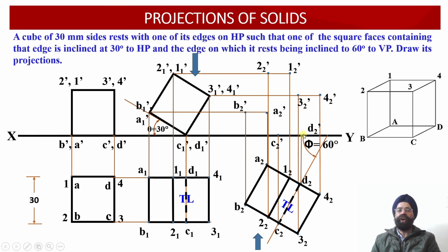But which of the edges will be drawn using object line? Which of these edges will be joined by using the hidden line? That we need to evaluate. Now let us look at this plan projection view. When the observer is going to look at this plan projection view from this orientation, A2 is the point which happens to lie farthest away from the observer or nearest to the plane. So anything joining A2 should be drawn dotted unless it is going to appear in the boundary.